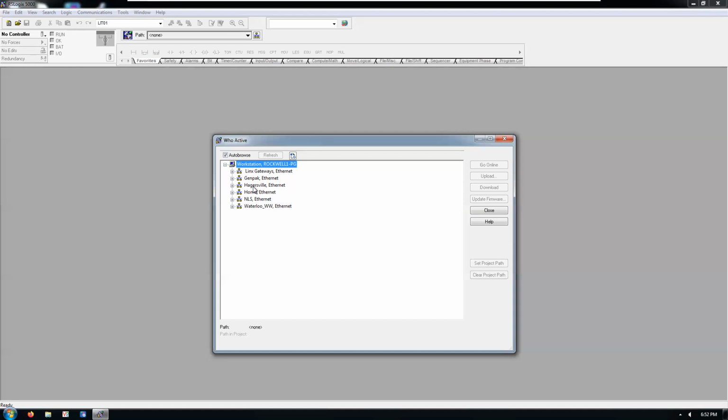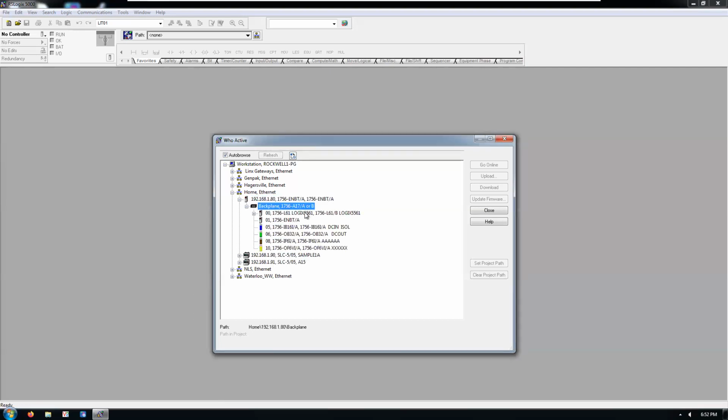I've had some luck with the Omron software and the Allen Bradley software, but nowadays the best way to do it is get some VMs and spin each VM up for each different programming environment that you have. And then that way you're less likely to have issues with software conflicting.